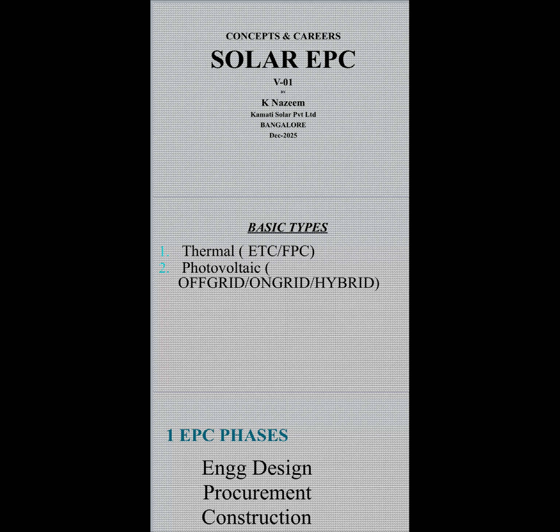That is, we'll be using huge mirrors to focus the sunlight on a centralized beam, and that centralized beam will heat up the salt in the tower, and that molten salt heats up the water to generate steam, and that steam in turn drives the turbine, and the turbine will generate electricity. So this is basically thermal. Now coming to photovoltaic, here the sunlight is converted to electricity.